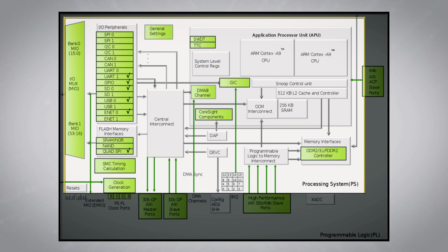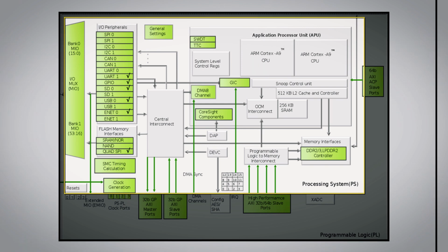All these components can be used at the discretion of the software that's running on the CPU, like the bootloader or kernel, and you have the DTB file, which helps the software set proper configurations for some of these hardware components. Let's go step by step here, starting from when you first turn on power to understand the flow of what the PS is doing and how it's loading the software.